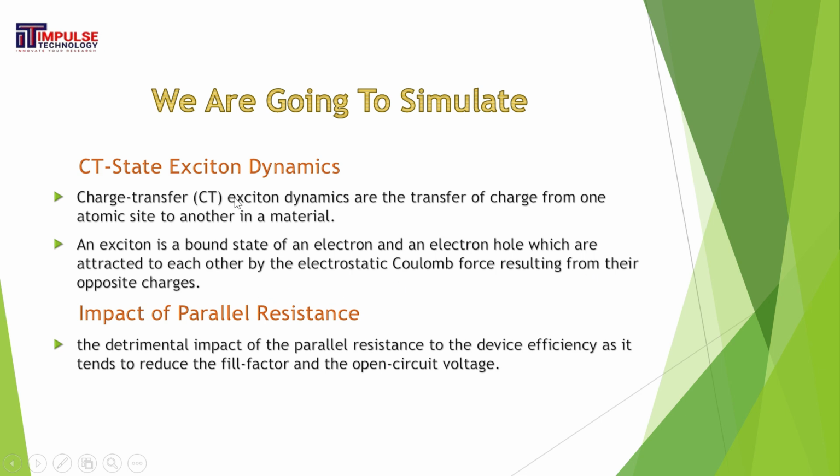Basically, I will create a layer structure of the solar cell. Then I will show the charge transfer exciton dynamics, how the charge transfers from one band to another band. In the similar structure, I will introduce series or parallel resistance. Then we will see the impact of the parallel resistance on the device efficiency, as it tends to reduce the fill factor and the open circuit voltage. So in Setfos, I will create a layer structure solar cell considering some layers. Let's move on to Setfos.